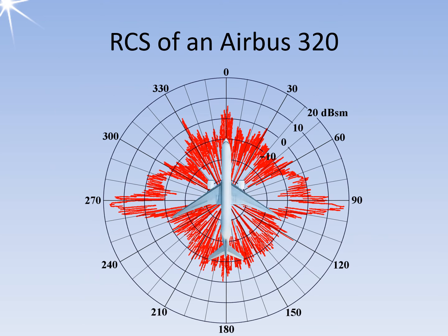This means that the amplitude of the echo signal fluctuates considerably even with very small changes in the aspect angle. These fluctuations can be in the range of 30 decibels. Due to the large number of influences on the result with complex surfaces, these fluctuations can only be analyzed statistically as a probability distribution. Probability distributions are typically defined in terms of the probability density function.